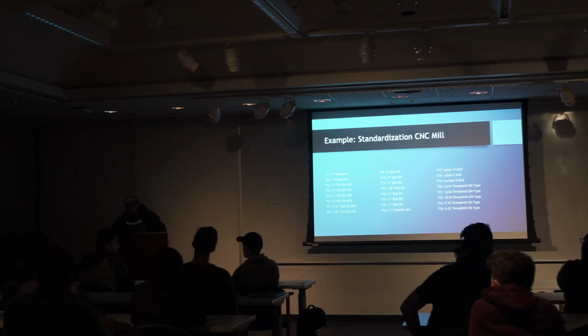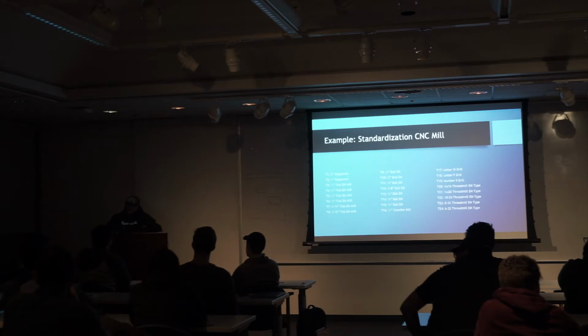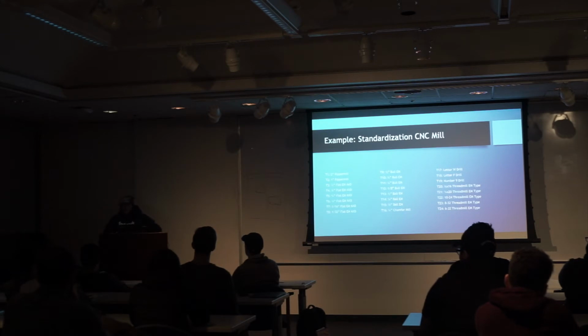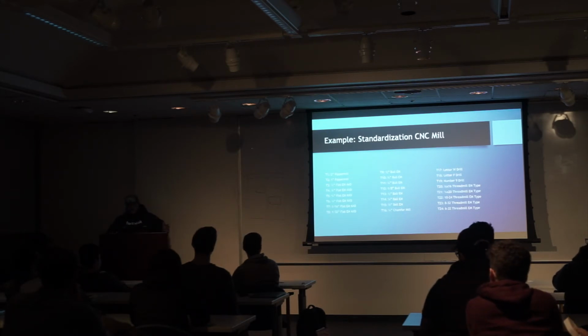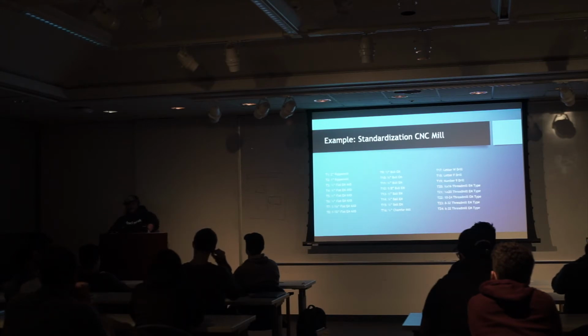Anyone else's thoughts? How do you go about standardizing features like wall thicknesses or corner radii if there's no numerical data available or historical, like if it's something you can't find information on? So corner radii is usually going to be defined by the tool, right? If we look at tool 3, which is a half-inch flat end mill, it can cut 4 times diameter. That means if you have a pocket that is 2 inches deep, the minimum corner radius I could put on that is half the tool, right? Because that's just how milling works.